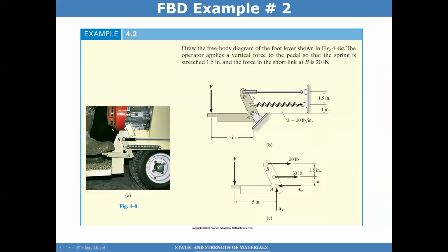And so to approach it, I have this lever being drawn. This is what I'm interested in, this lever right here. So this is your lever. And then any boundary conditions applied to that lever should be removed. So I have this pin attached to this lever. I remove the pin, and what should be reacting at that pin is two loads, AY and AX. I don't know them, but we do know there are some loads that could be replaced in this pin.